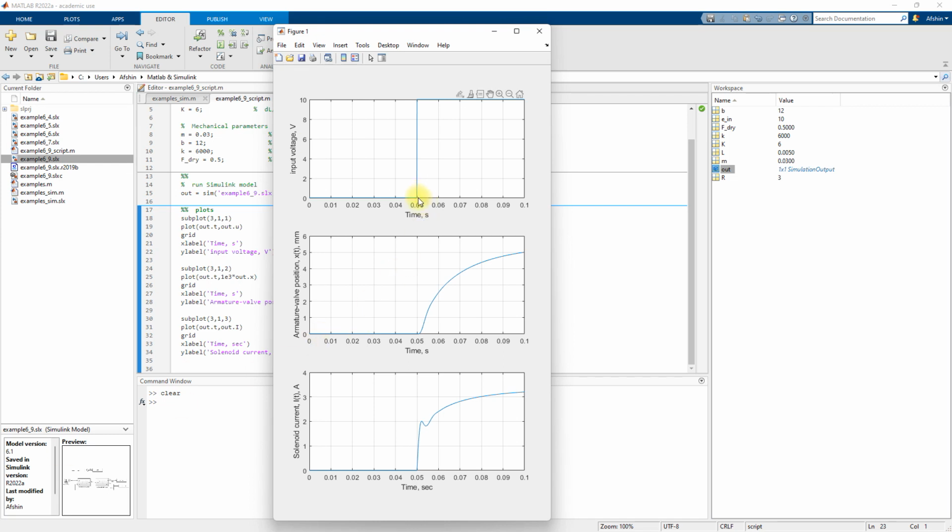And we should see this time that because of the finer time steps that we have, we are getting an actual step instead of a ramp for our input. So this is always good to check your inputs, outputs, and plot them this way so you can see the changes, you can see if the behavior is as you're expecting, or if not, what you can do to fix it. And in general, a good way to communicate your result to your audience.